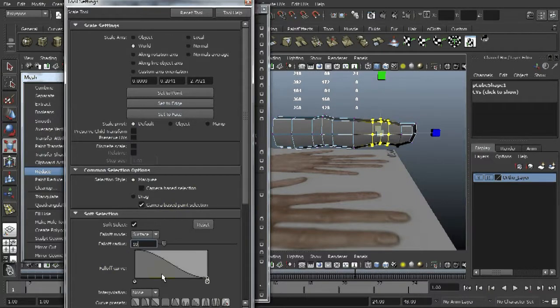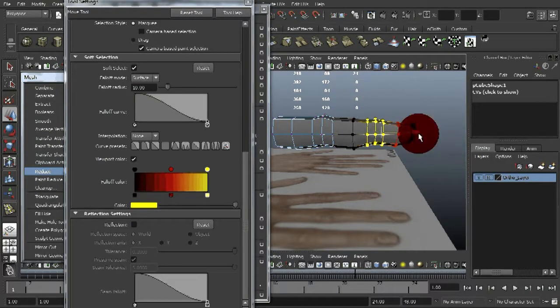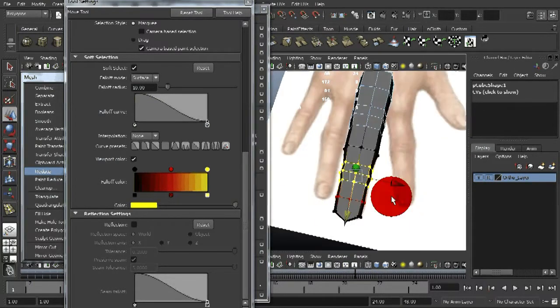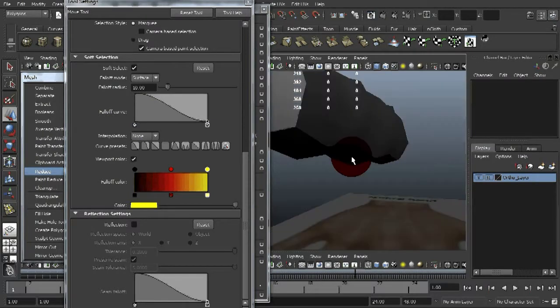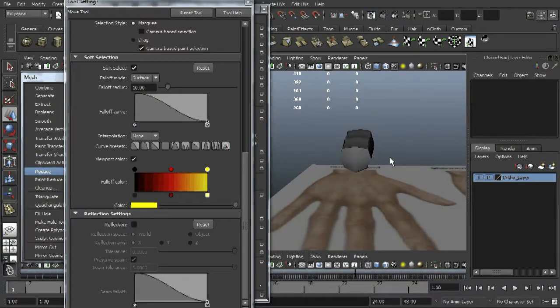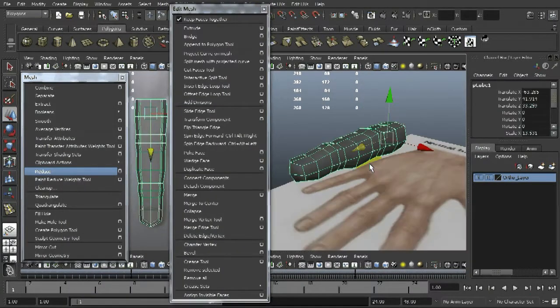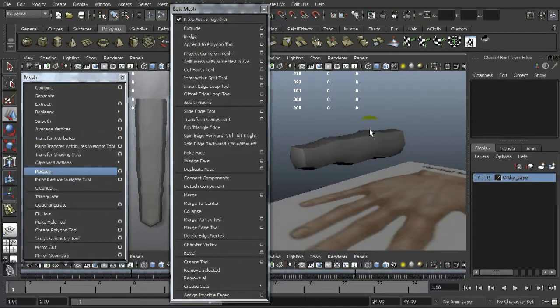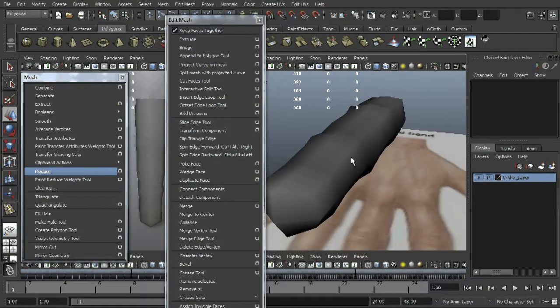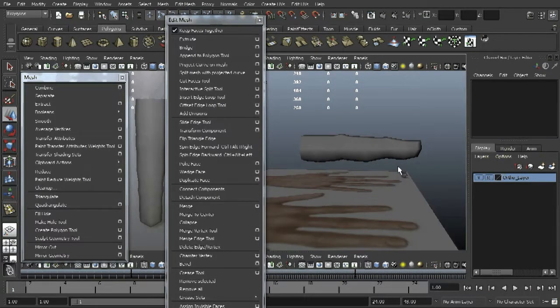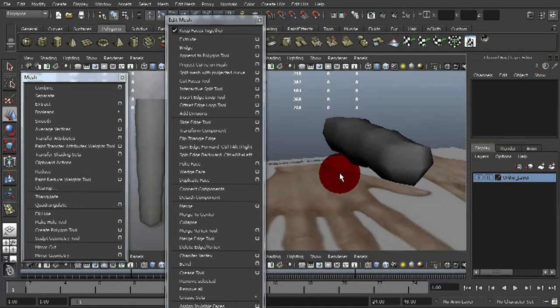Now, you've got your extrude tool, you've got your add edge loops tool, and you can select different levels of your object in order to modify the different levels, to move the different polygons around and whatnot. You also have to take into consideration the smooth and sharp edges. So what are smooth edges and what are sharp edges? Well, they're actually similar to 3D Max's smoothing groups.